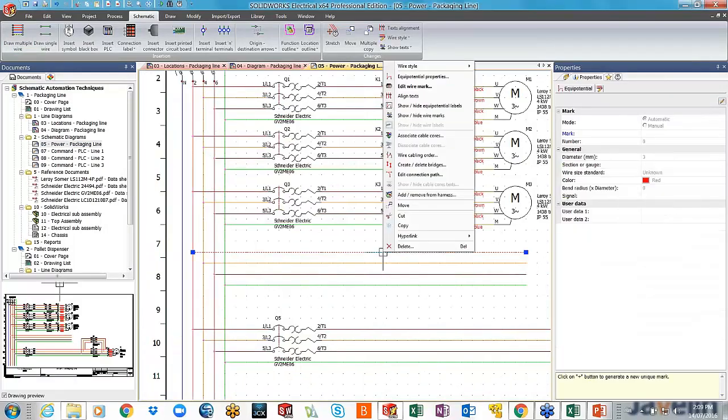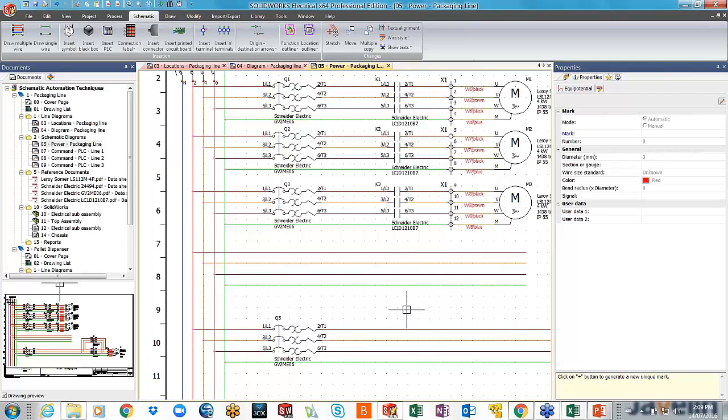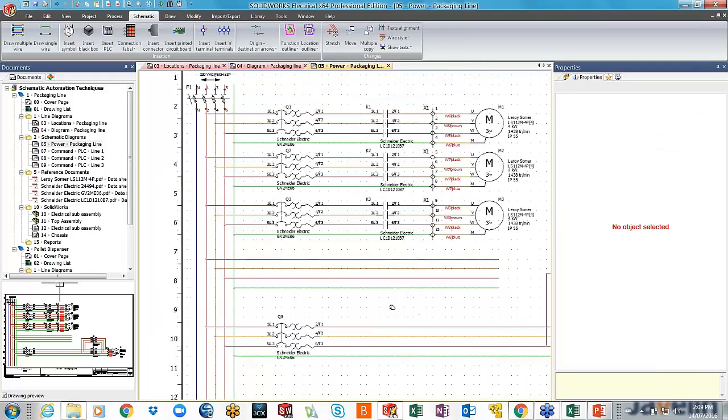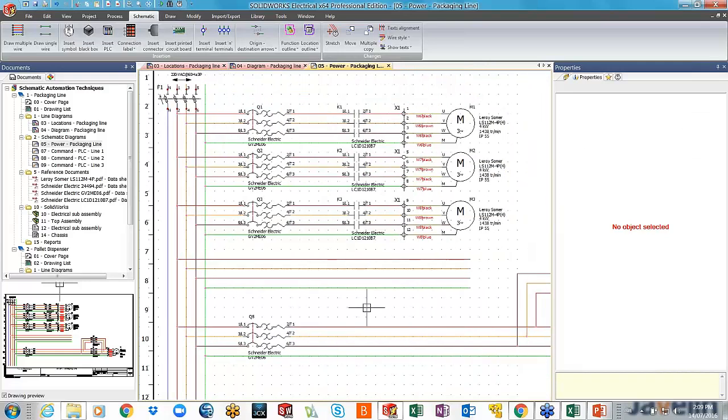If you right-click onto this, you actually have information related to a wire. As you can see, it's asking whether I want to add some equipotential properties or any other, or add a cable to this. This particular representation of the wires has intelligence behind it. Now, this is still the basic or the lowest level of drafting possible in SolidWorks Electrical.